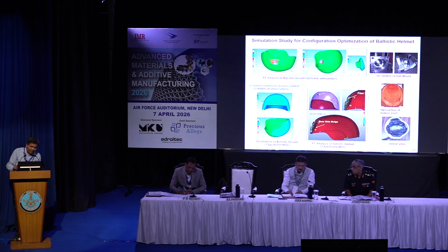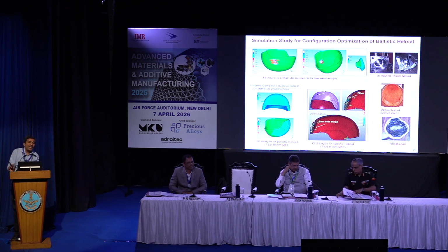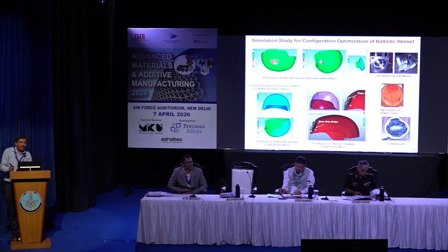We have studied different types of simulation for the helmet. We have made all 3 types of helmet, like stopping the 9 by 19 mm bullet. It is already in use by the services, and we have also made a helmet that can stop the AK-47 MSC and the hard steel core bullet. But the only thing is that the traumatic brain injury effect is also underway. Unless we have a complete study, stopping the bullet with backface deformation of less than 30 millimeter for the helmet is not an issue with the hard steel core bullet. But the only thing is the type of shock wave that will be transmitted.